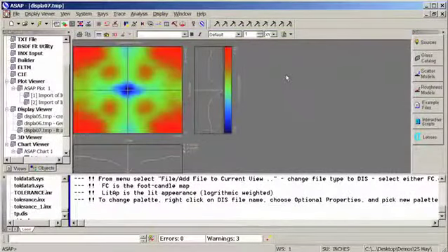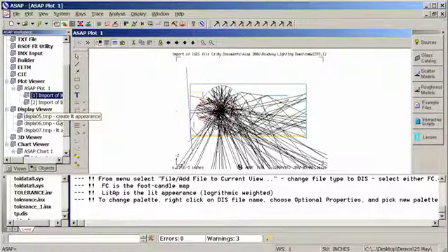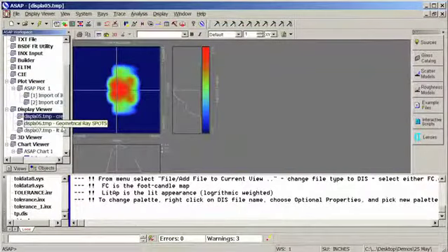Okay, some of the analysis we can look at not only is looking at the geometry and a visualization of the ray trace, but we can also look at lit appearance type data. And with the lit appearance information, we can look at it in a linear scale, or if it's going to be light visualized by the human eye, we might want to look using a logarithmic scale that more represents the ability of the human eye, so maybe a log scale of 2.3 to 2.5.